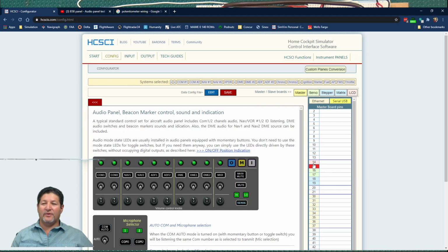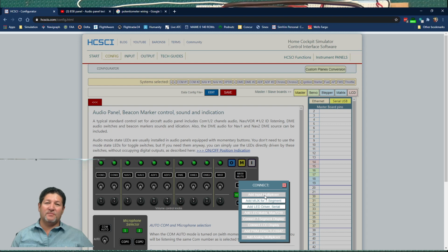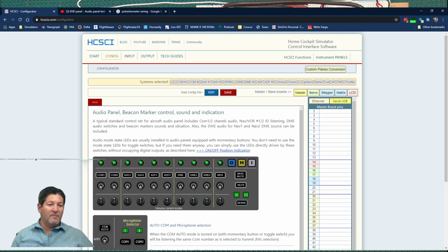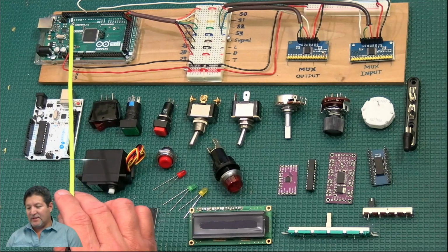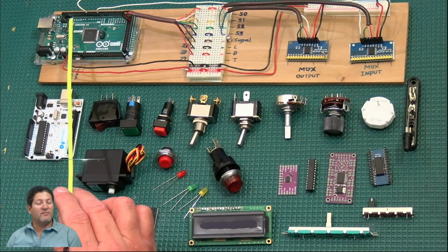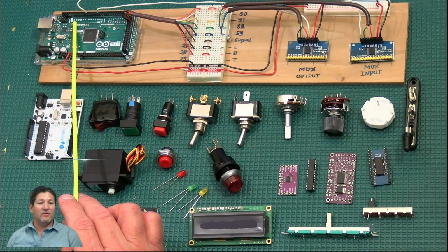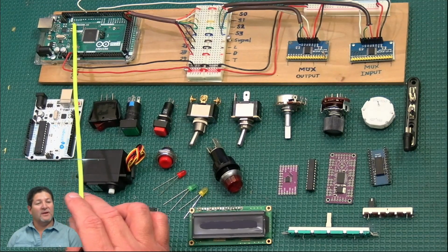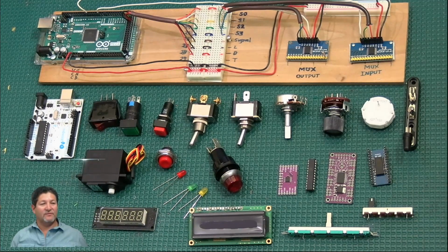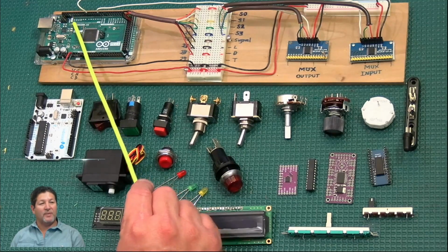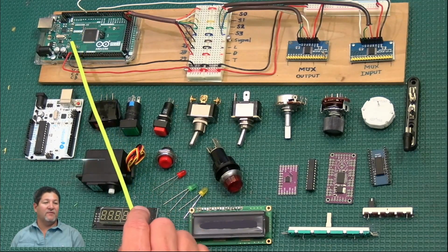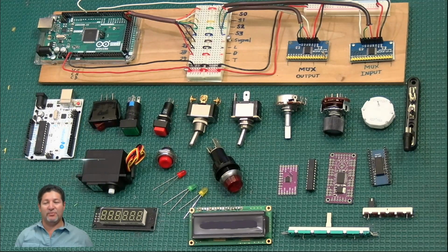But once again, if we go to number 13, you see that the input multiplexer option is grayed out because you cannot select it. And I believe the reason for that is because if we look at the Arduino, there's an LED that is linked to pin number 13, and as we might know already, an LED is a diode, so it only allows current to flow in one direction. So if you're trying to put an input on that pin and it has to go backwards through the LED, it cannot flow. So that's why you cannot assign an input on that one. At least that's the way I see it.